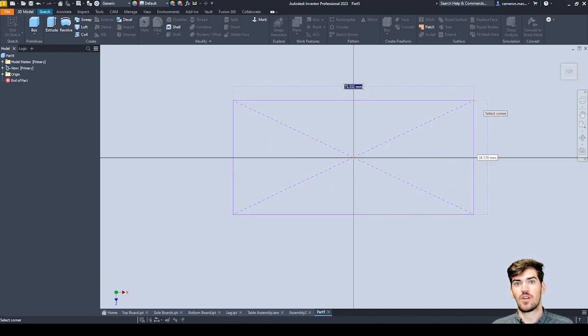And right from the get-go, we're going to now start naming each of our dimensions. So we know, looking at it from the top, from above, and with the correct alignment, we're going to have our width first, and we're going to have our depth of our table. So the first value we put in here is our width. So I'm just going to type in width is equal to 800. It's going to go black, which means it's confirmed, it's able to have that. If it's red, it's unable to confirm that that's going to be added to our parameters.